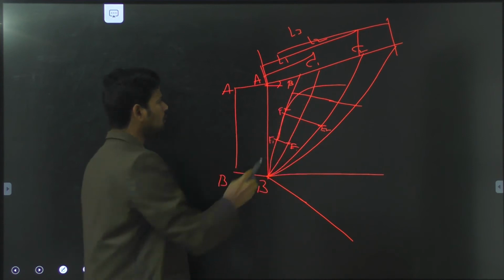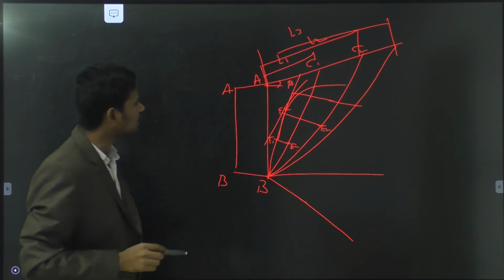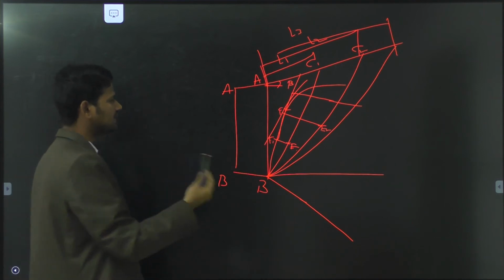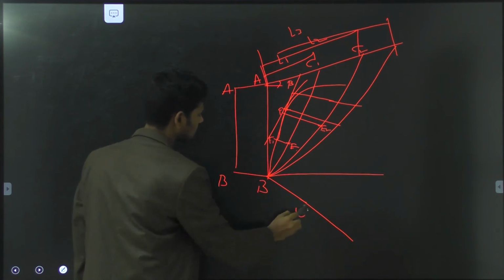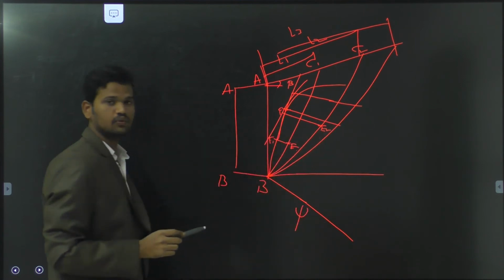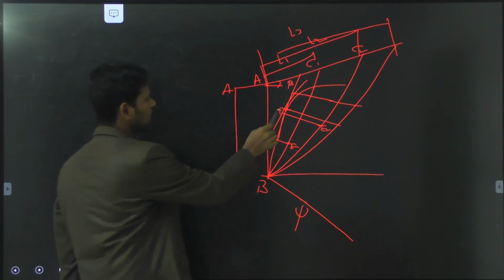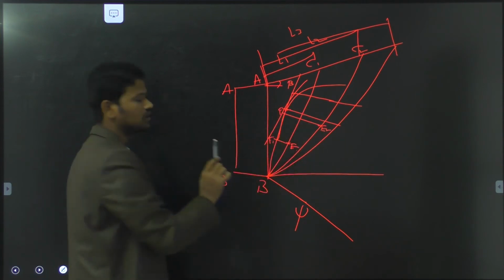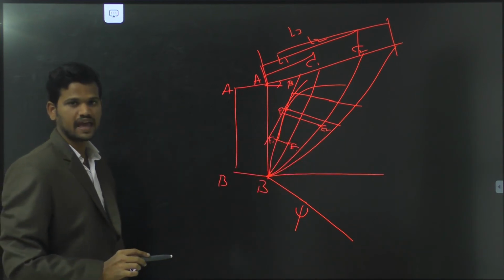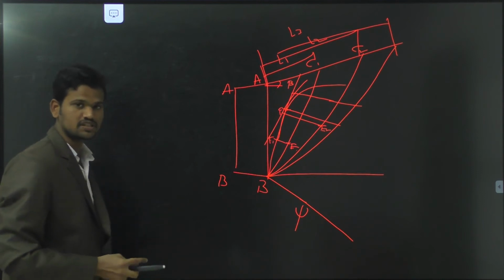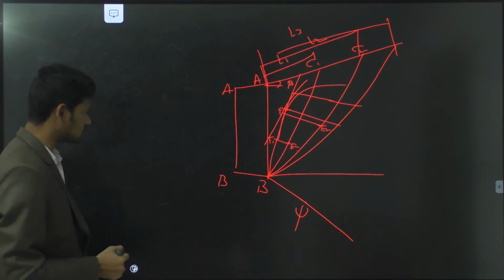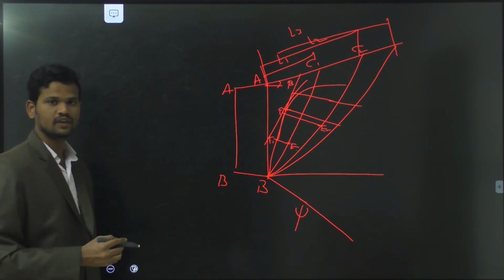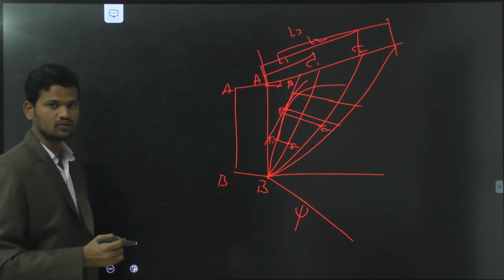After drawing all the points, by using a curve we are drawing through all these particular points. For these points we are drawing a curve where it touches, from this point to this J line. Okay, this is your J line. From this J line we are drawing one more line. This portion of the triangle gives the active earth pressure acting on the wall. That active earth pressure PA equals half into gamma into H square. This is how we graphically construct the active earth pressure.